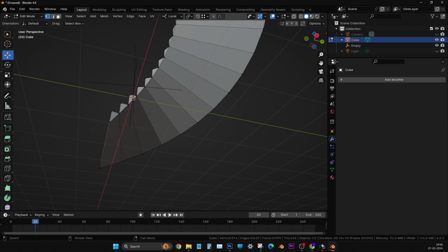Third, near the edit, no, edit mode. After the edit mode, vertex mode, face mode, last one. Now select only one face. First face, this perimeter we are selecting. Go to select menu up. Select menu, select similar, perimeter.